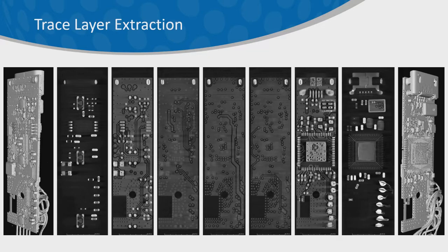So we can compare these against print files. We can extract these traces as image files, threshold them, and compare them right back to how the part was built. There are also other tools as well. In the end, a lot of people want to go back and generate a full net list and parts BOM. And that's part of the process.